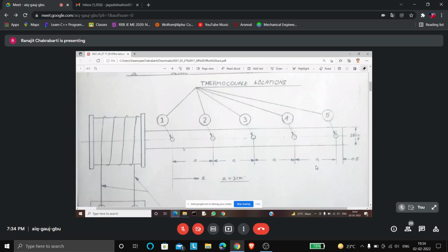We are also considering that in the R direction there is no gradient of temperature, so there is no heat transfer. In the theta direction also, there is no gradient of temperature. The entire temperature gradient remains in the axial direction, Z direction or X direction. Let's say X direction. The temperature gradient exists, so from one cross section to the next cross section the heat transfer occurs, and from that to the next cross section.